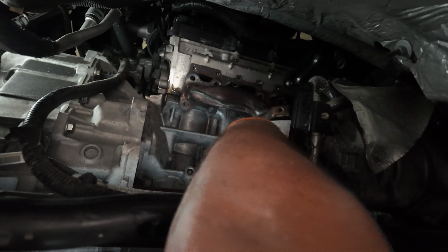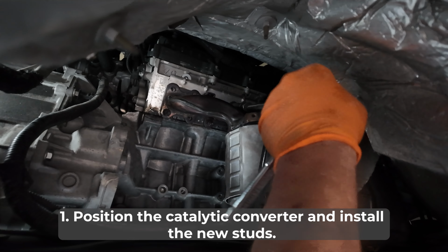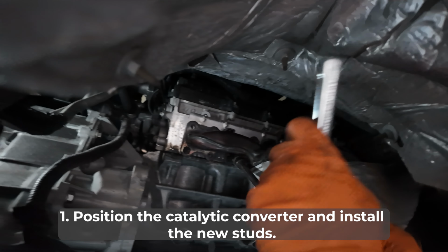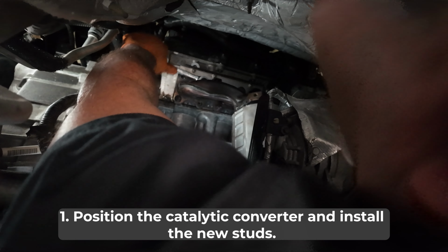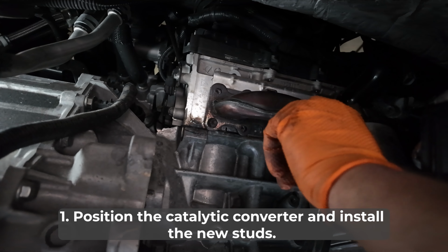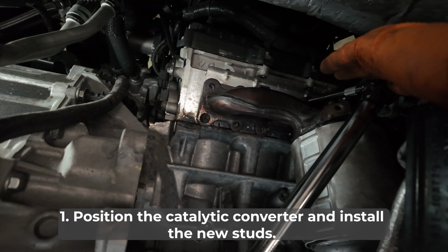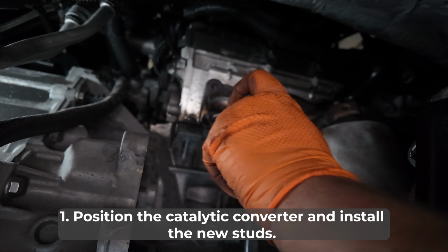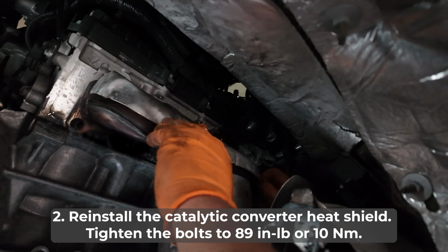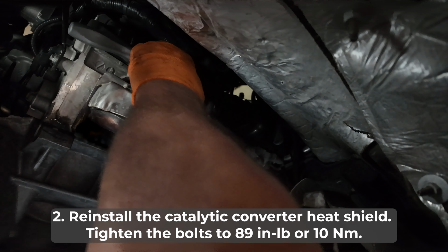All right, let's go ahead and install the new catalytic converter. First, install the new studs. With a new gasket in place, install the catalytic converter and secure it with new nuts. This ensures proper seating of the gasket to the cylinder head. Now reinstall the catalytic converter heat shield and tighten the bolts to 89 inch-pounds or 10 Newton meters.